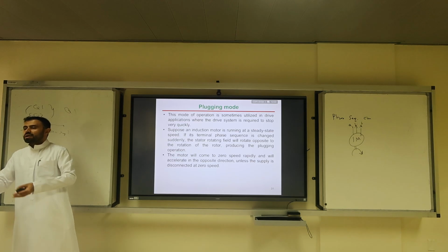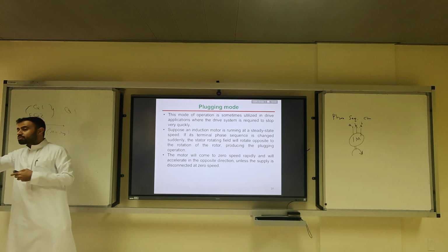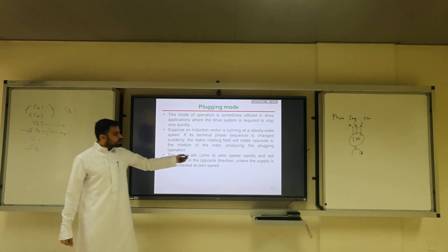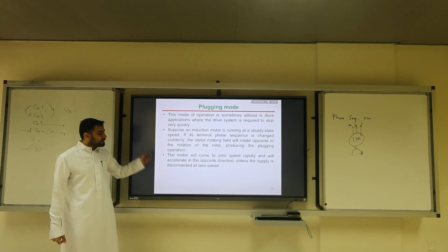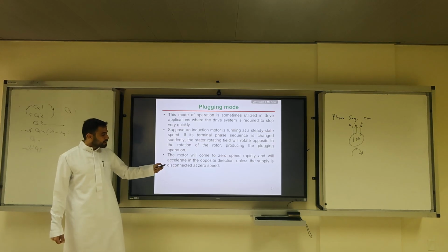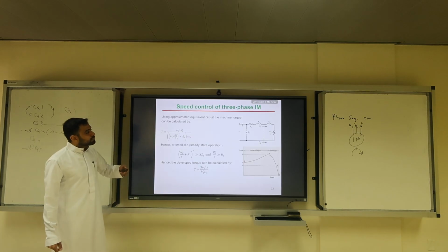The phase sequence would make the RMF rotate in the opposite direction, making the slip negative. The motor will come to 0 speed rapidly and will accelerate in the opposite direction unless the supply is disconnected at 0 speed. So this is a type of control for plugging mode.